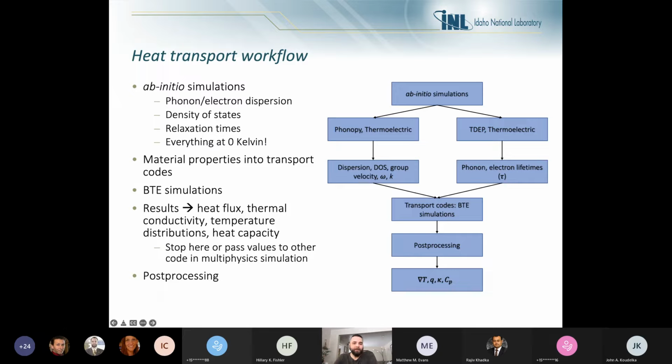So one big important thing to grasp here, and this is going a little bit deeper than we need to, is that when these properties are generated by these simulations, they're all generated assuming that nothing is moving. So atoms are not vibrating. I said earlier that everything is vibrating because it is at some temperature. Well, the assumption is used that materials are at 0 Kelvin, so atomic motion has ceased, and they can perfectly figure out what the spectra of phonons and electrons might look like.